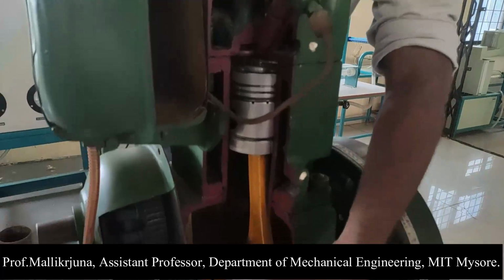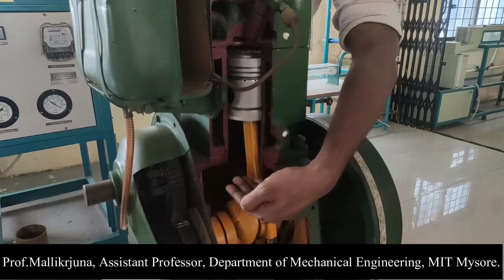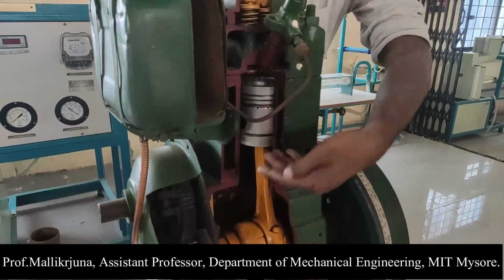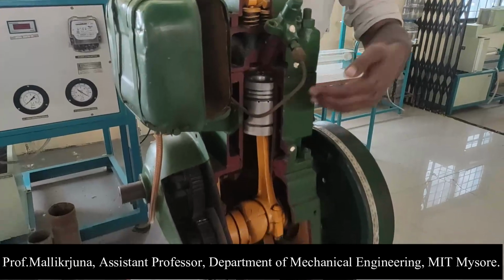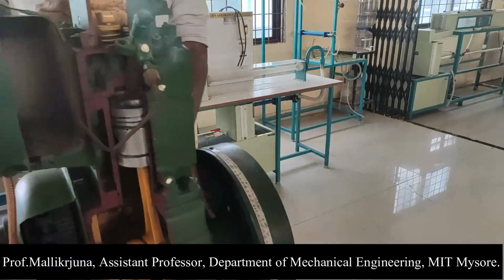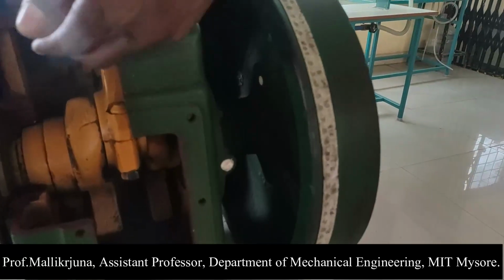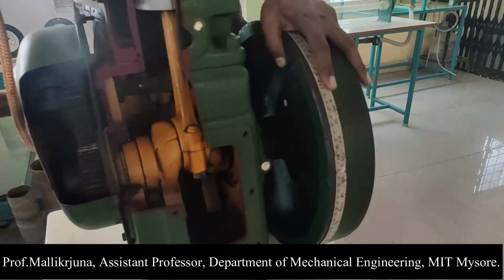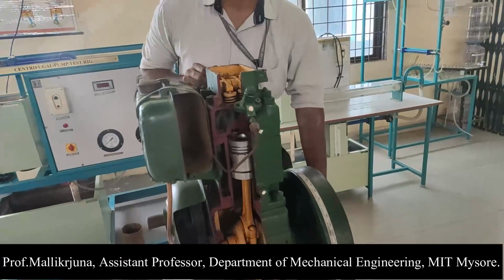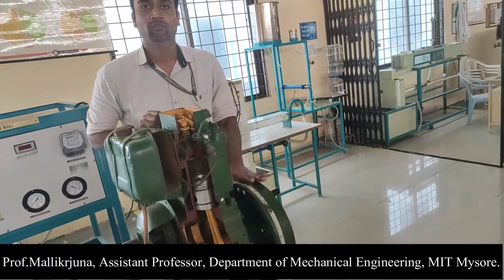The piston moves within the engine cylinder in a vertical fashion, I mean it reciprocates inside the cylinder, and that reciprocating motion is supplied onto the flywheel through the crankshaft. Here it is, the crankshaft. So that reciprocating motion of the piston is converted into rotary motion of the shaft. So now the shaft is attached to the flywheel.